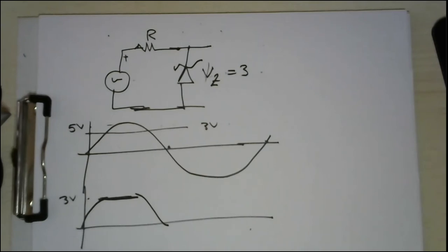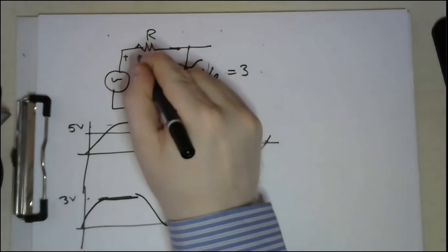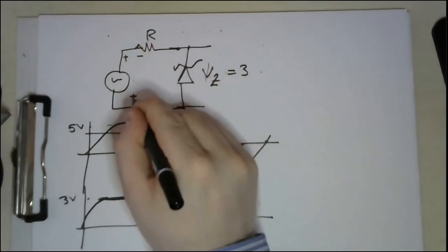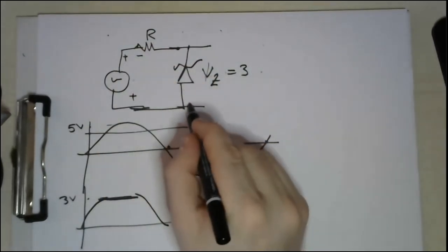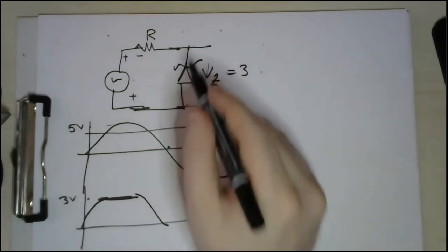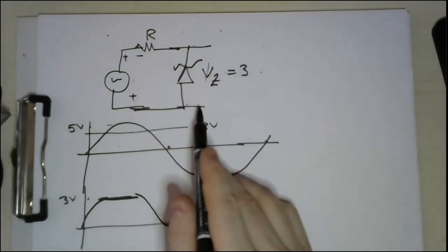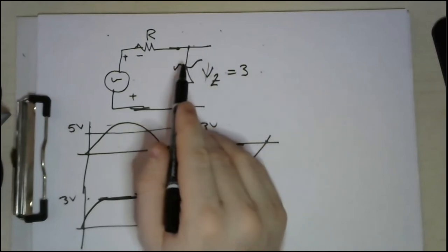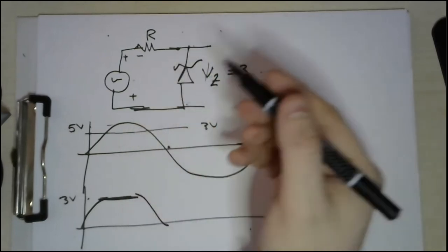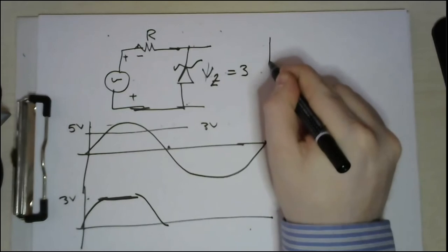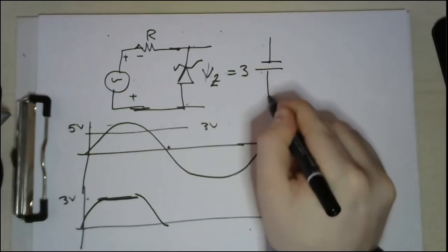What about the forward bias? It's a very normal diode. So whenever you have, I mean in the negative half cycle, now the voltage here is positive and the voltage here is negative. The current is flowing in this direction from down to up, and then this diode is in a forward bias. Then you are going to replace this diode with a battery as usual.